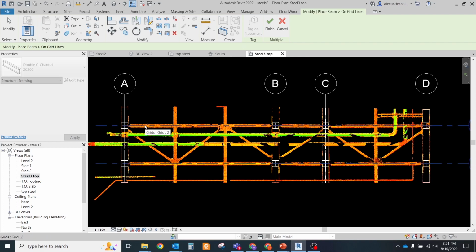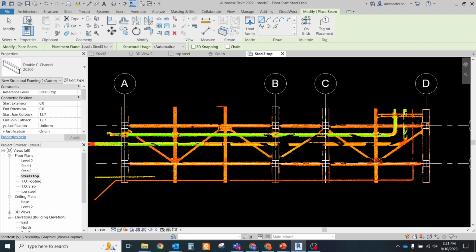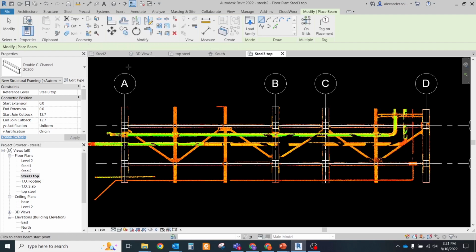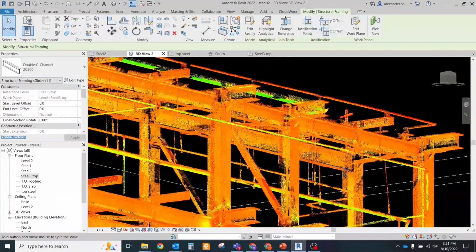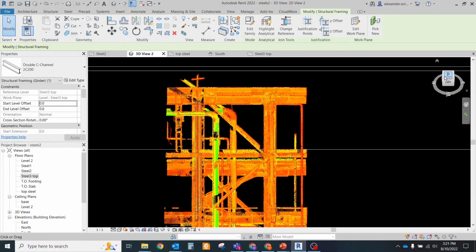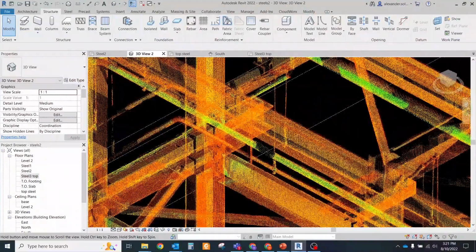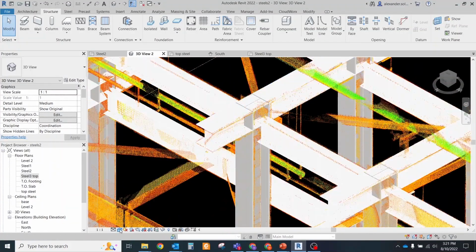And when we're working with point cloud, we are trying to create a digital copy of the real environment, but Revit doesn't work properly if all elements are generated with a small lean and with slight deviation from the X, Y, Z axis. That's why, working in Revit with point clouds, you should always find a compromise between accurate and right modeling. Generally, steel elements designed in Revit are based on levels and axis position.